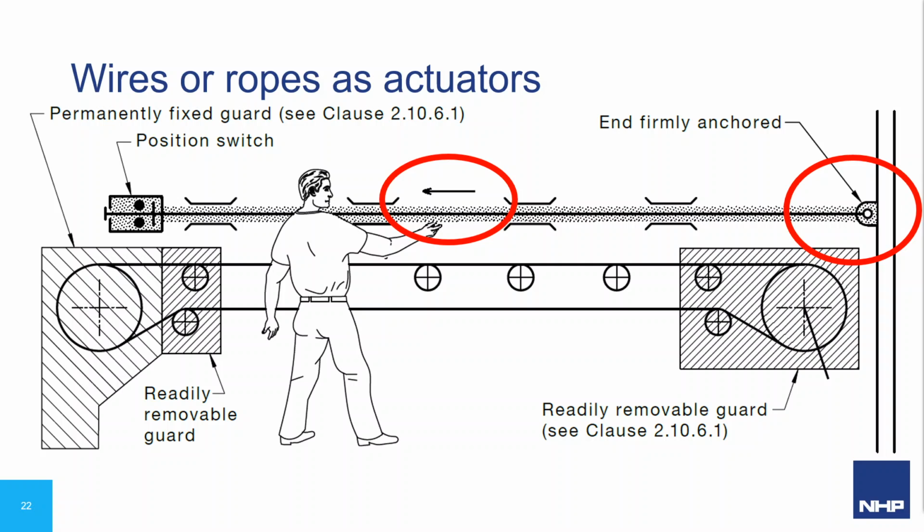The requirement of being able to pull a rope in any direction and generate an emergency stop command has implications on how the rope is affixed to the machine or other structures. Let's look at an example where the rope is firmly anchored on the far right end of the switch, which unfortunately does happen in some installations. Pulling on the rope away from the conveyor or perpendicular to the axis of the rope will trip the switch as it's applying extra tension to the rope.